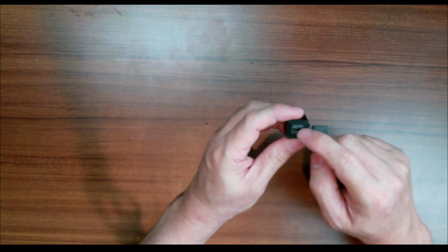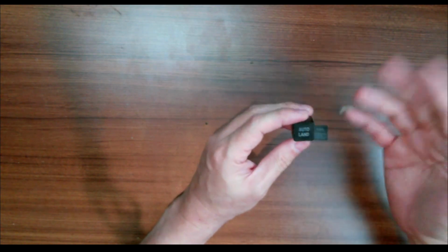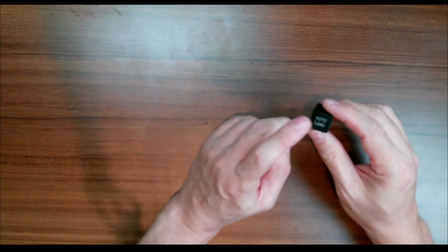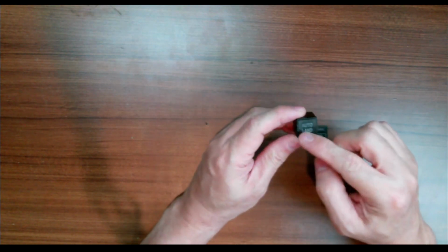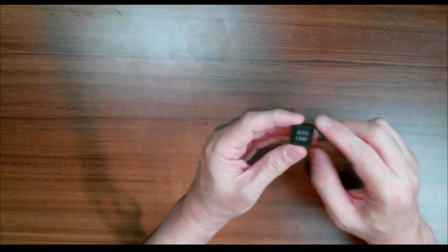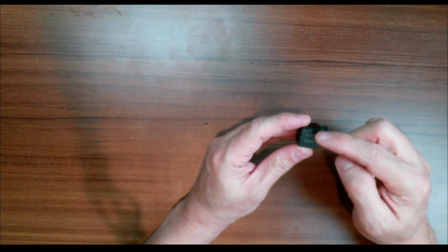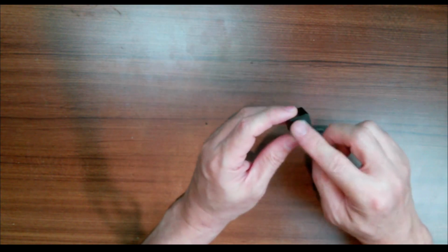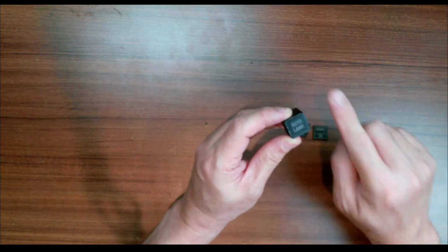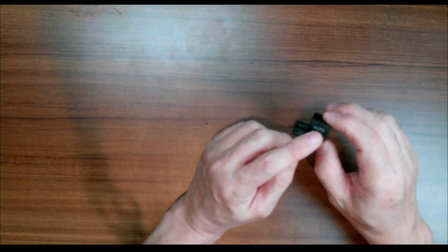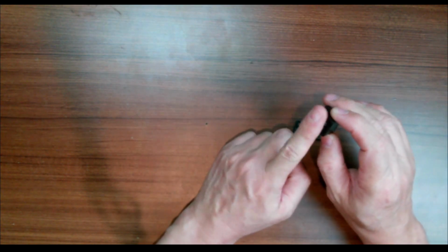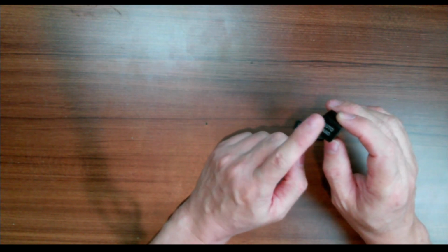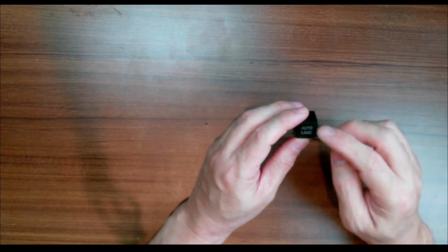A darkened film for the glass, a car automotive film, to darken your windows. So I put that film on top of this. It's quite okay, although sometimes it kind of peels off a bit at the edge, but you can glue it perfectly. You have to clean it up first with alcohol just to ensure there's no oil, and then you attach that film, darkened, I think around 25%.